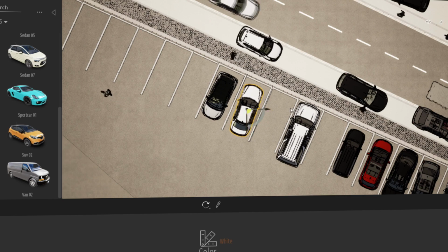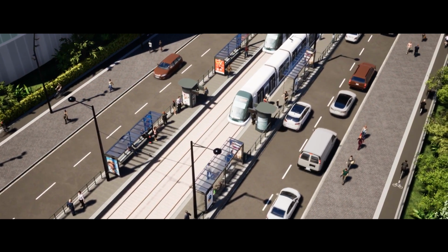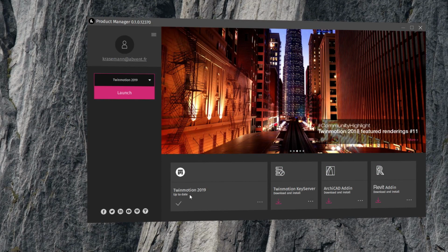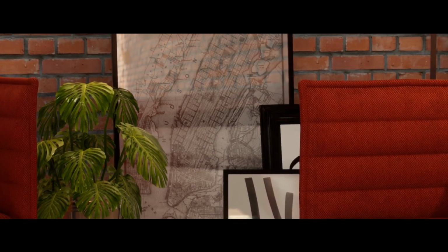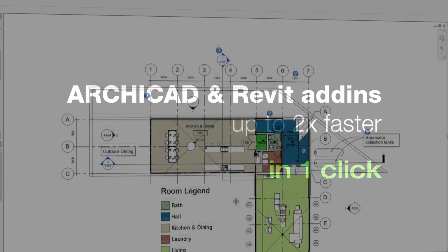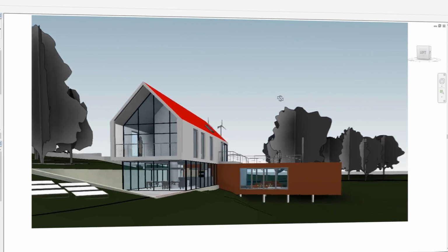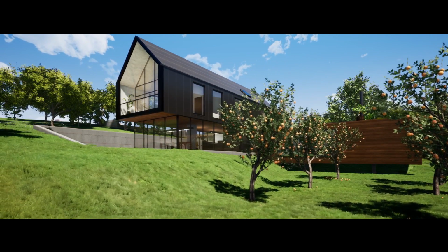Okay, another question. How can I add buildings that illuminate at night too? Those buildings are not natively inside Twinmotion. They were part of the project, so they were created in 3ds Max with just a texture, and when you select the material, there is an option which is day-night cycle, and basically, if you check this option, the material will start to glow once the sun comes down.